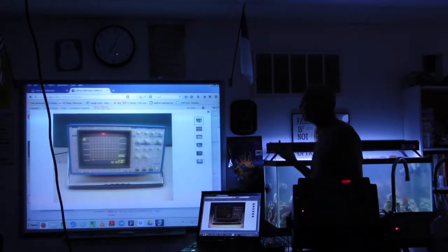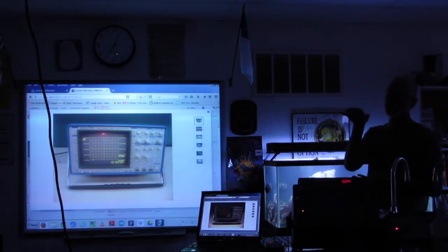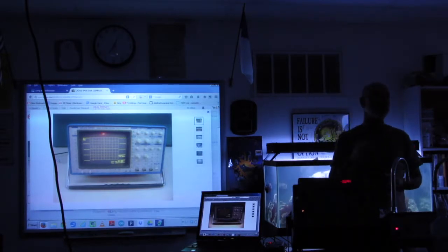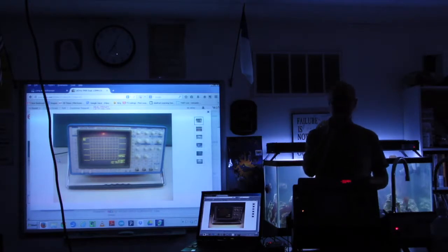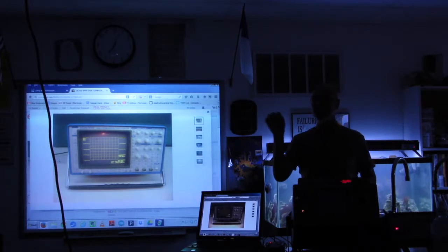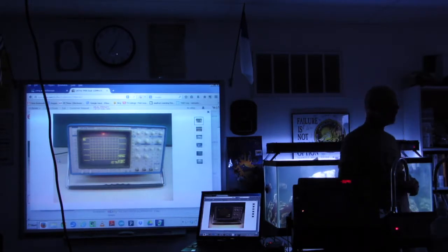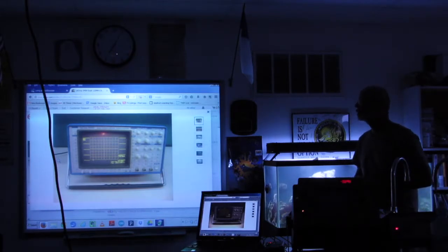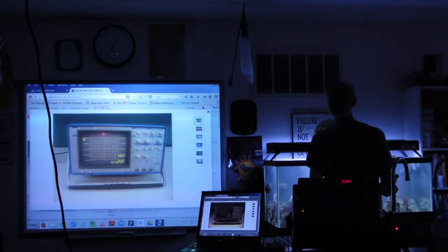In a digital scope, with an 8-bit digital scope, that gives you 256 pixels vertically. And so that means if your signal being displayed is smaller than a bit, then what you'll see is a tiny little square wave on the screen, because it's dithering between 0 and 1. Pixelated. So that's the limit.